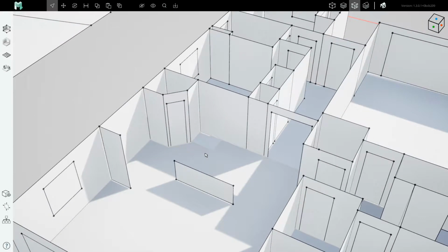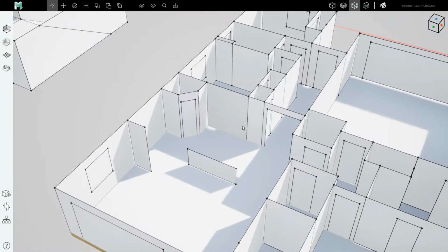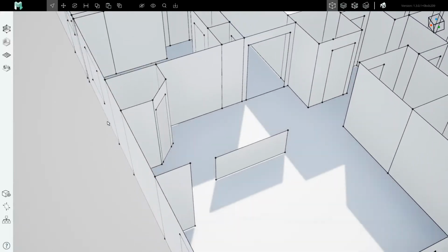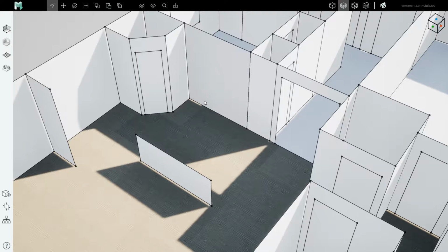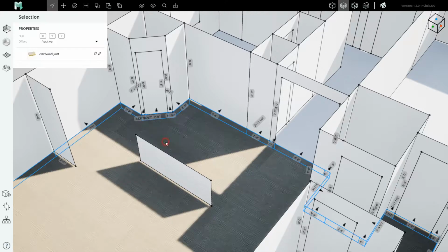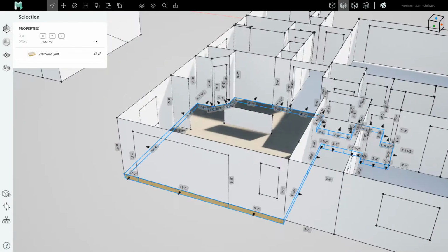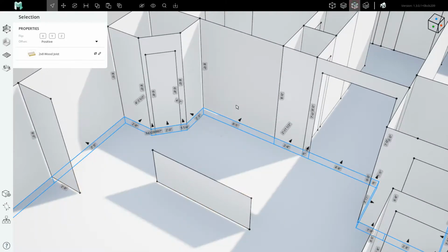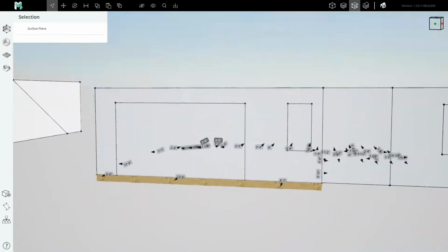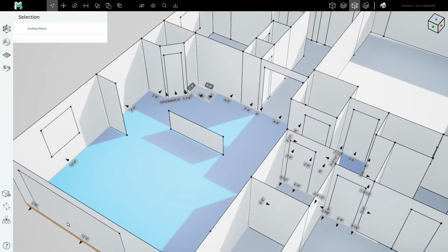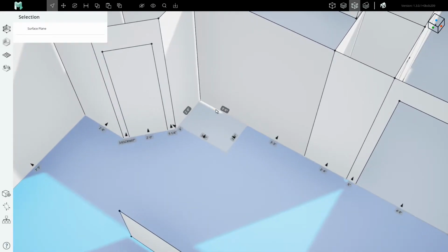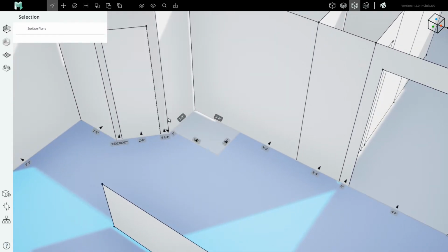The difference between a surface graph and a massing graph is that the massing graph, as seen in the first view, is a three-dimensional set of connections between planes. The surface graph is attached to the face of a separator. This floor here is a separator object, and we are now looking at the surface attached to its top. Look at me, I'm giving away all sorts of important information from future videos, but trust me that we will go over what a separator is and what a surface graph is in further detail in future videos. You can just Google for those topics, separators and surface graphs.